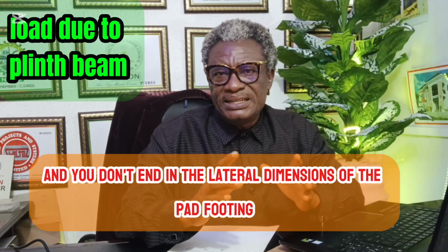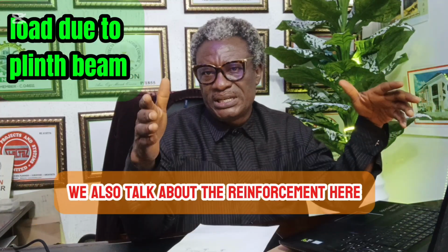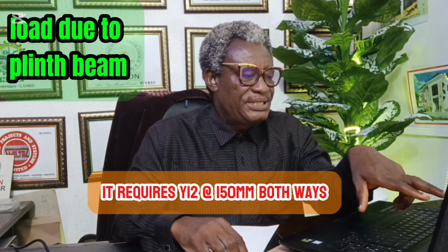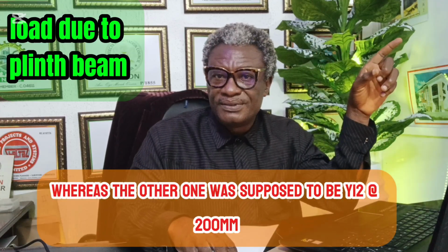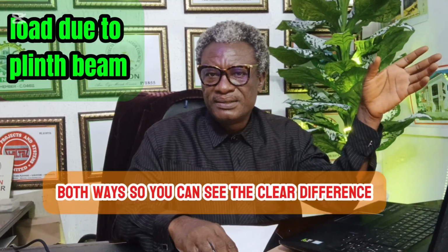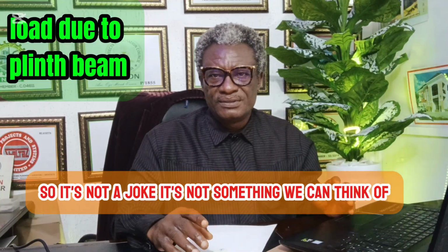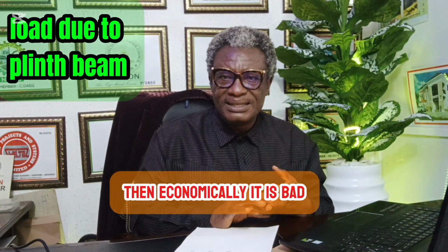And it doesn't end in the lateral dimensions of the pad footing. We also talk about the reinforcement. Here it requires Y12 at 150 mm both ways, whereas the other one was supposed to be Y12 at 200 mm both ways. So you can see the clear difference. It's not a joke. So structurally, it is bad. Then economically, it is bad.